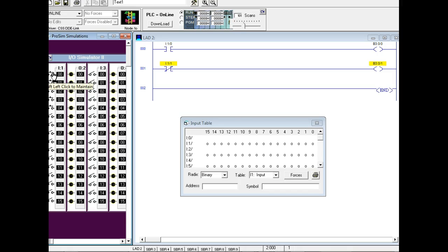But when we bring that 1 and that 0 into a program, is a 1 true or is a 1 false? A 1 is whatever you make it. In fact, the RS-232 interface uses a negative voltage for a 1 and a positive voltage for a 0. So it's up to the program to decide what is a true and what is a false.